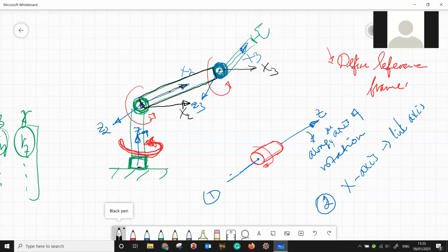Because for the first joint, you have the freedom to select the x-axis along your desired direction, since there is no link for joint 1. So I could say x1 is here. Because I'm going to apply some trigonometric relationships, I would like to simplify as much as possible. So how do I simplify? At least for visualization, I will assign x1, x2, and x3 parallel to each other.